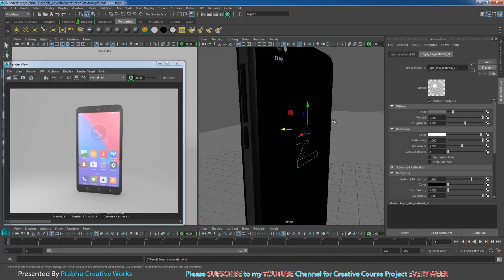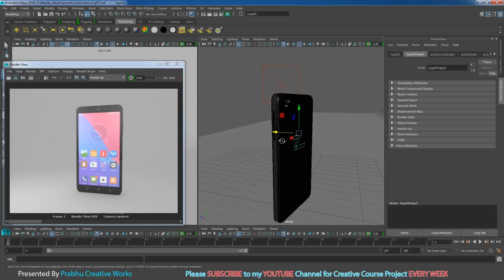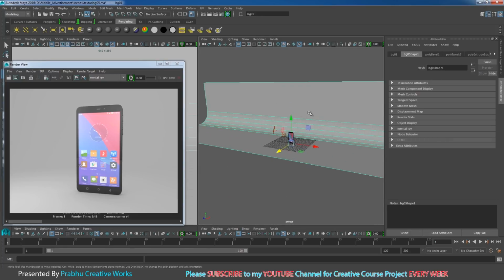Now I want to select this view, keep this image for comparison and click render. Okay, now we got the specular color highly reduced for our objects. Now I want to give a background of ambient occlusion. So I will select my BG mesh.